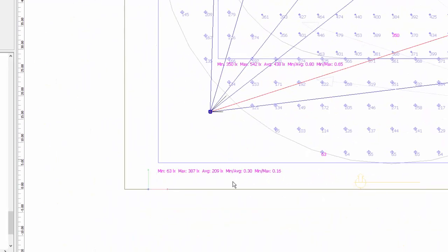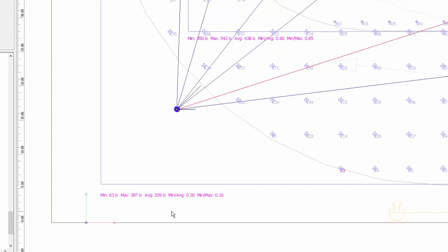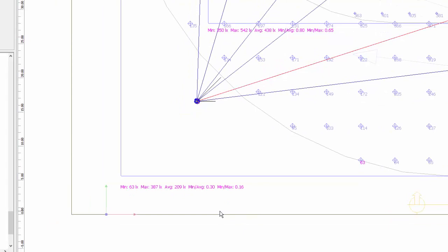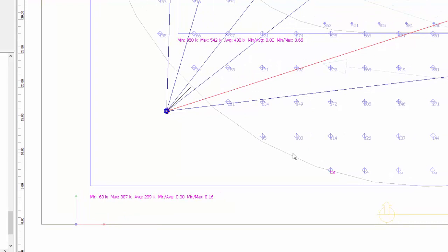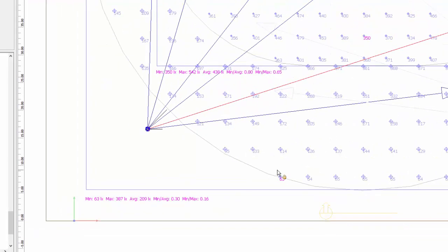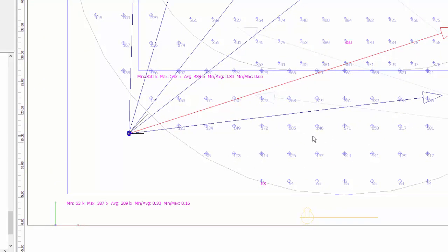Now, our next problem is the outfield. So, it's 0.3, and the requirements for the outfield is 300 lux with 0.6 overall uniformity, or 0.7 if we can do it. So let's go and achieve it. So for now, I will add maybe one more. I will copy this one, Control C and Control V.